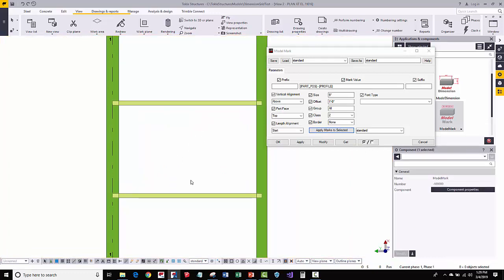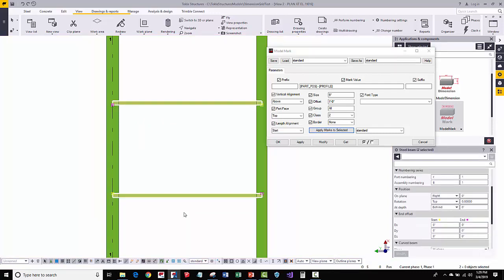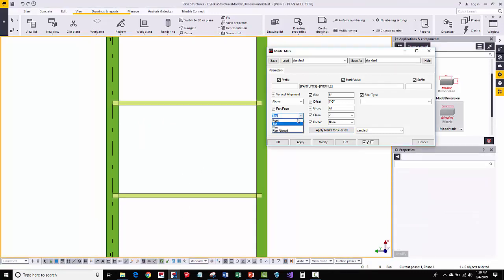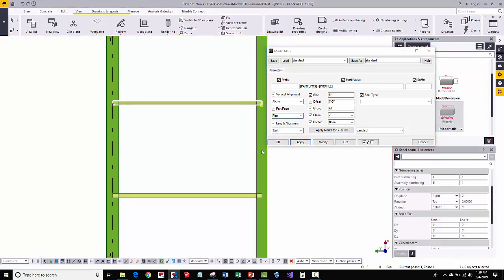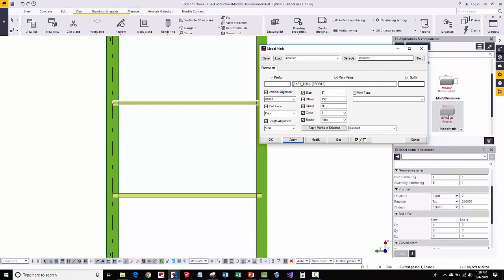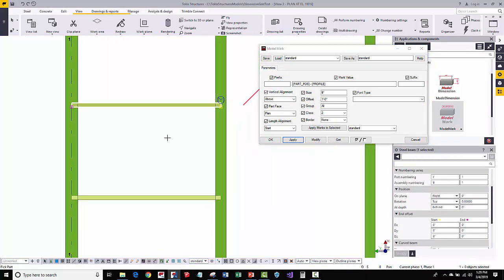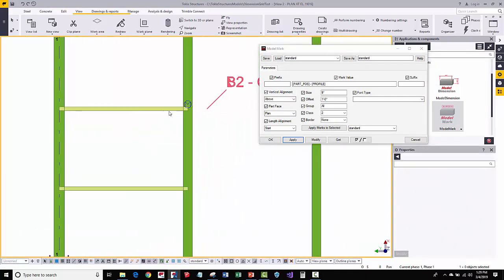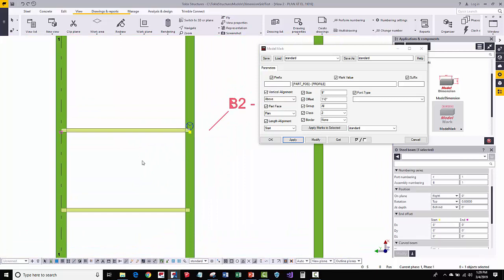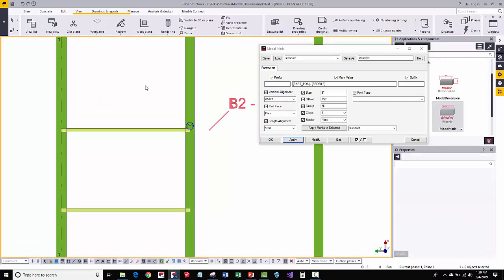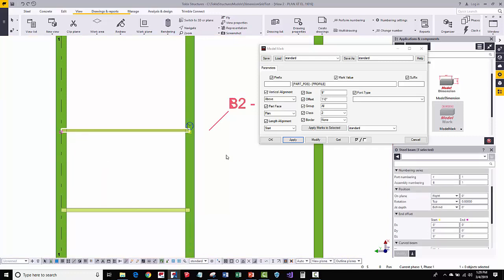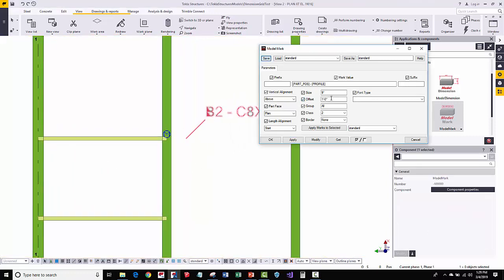To do that, we can do this a couple different ways. We can again select on these. Let's do plan as an example, and we still want it to be towards the start end of the piece. Now I'm just going to activate the component, pick on the part, and then it puts that in there. So whenever the beam is coming from right to left or top down, so it's kind of going the opposite direction of what you normally model, if you open this up, you'll see there's this offset here, and that's just putting this in so that it looks a little bit more cleaned up.